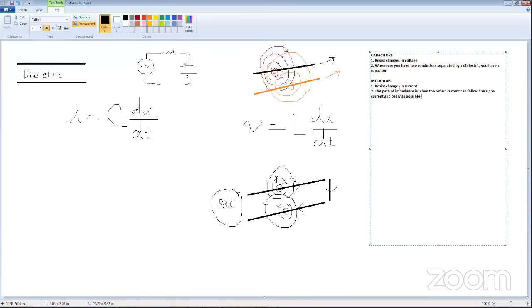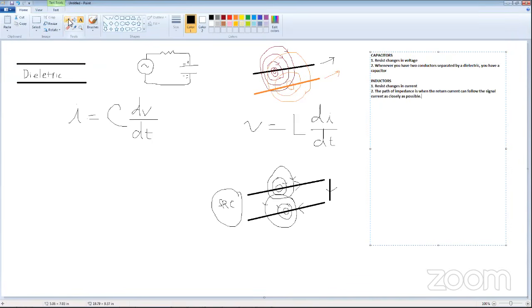Want to tell us a little bit about microstrips, Jorge? Yeah, so microstrips, the thing about the different topologies, those are the ones that are well understood. So you have microstrips, you have strip line, you have a few others. Basically, microstrip is when you have, and I'm going to go ahead and draw it because I can. So if you're looking at the thickness of the board, what you typically see with a microstrip is this is your trace, because that copper, as thin as it is, does have a thickness.